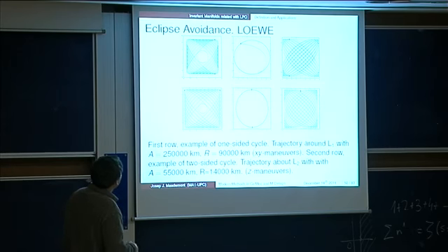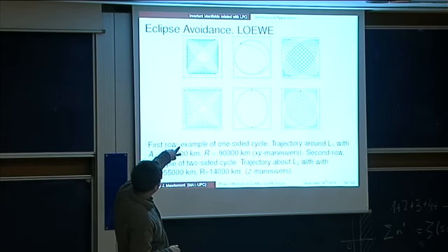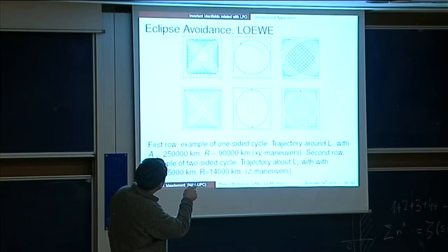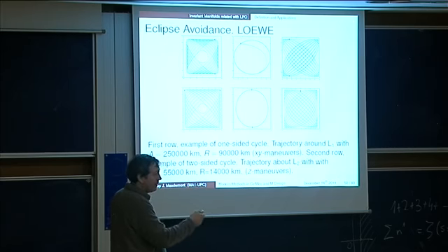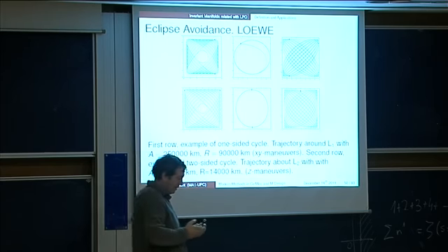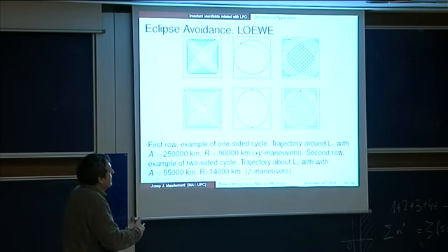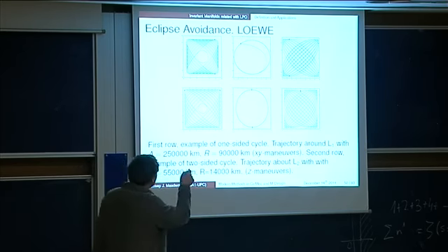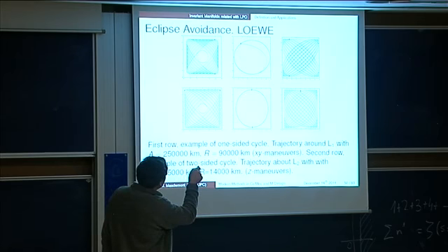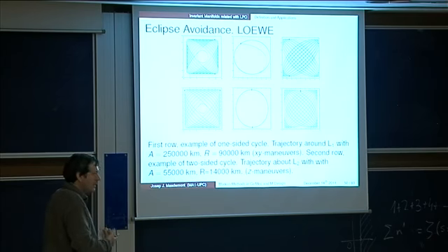And essentially what these kinds of maneuvers do, and you see here in the Lissajous we avoid the exclusion zone, is that the maneuver at some point, here, injects the satellite into the stable manifold of the same orbit, but it turns out that this stable manifold crosses, in position, the same Lissajous. So what we are computing essentially are the places where the manifold crosses the orbit itself.